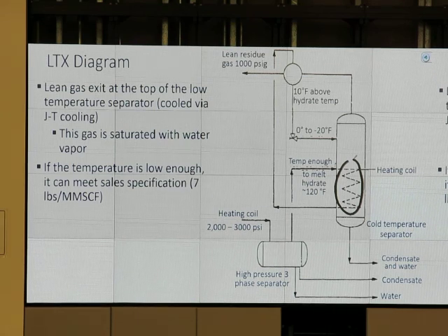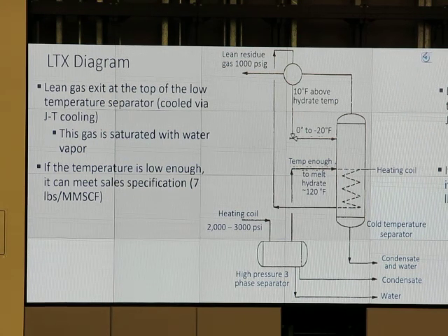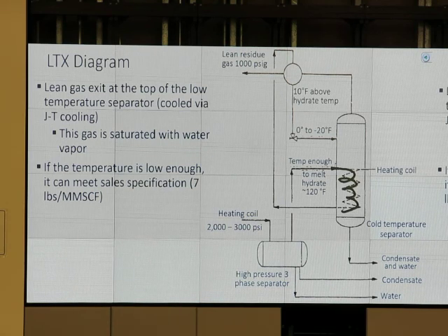We use heat from the gas stream to melt the hydrate. Okay, how will any of that happen? This means we have a coil, and heat from the coil has to go from inside to outside. That has to do with U value, right? And for heat, we have to use Q = U A ΔT_m to know how much heat transfer. And with that heat transfer, it will melt the hydrate.